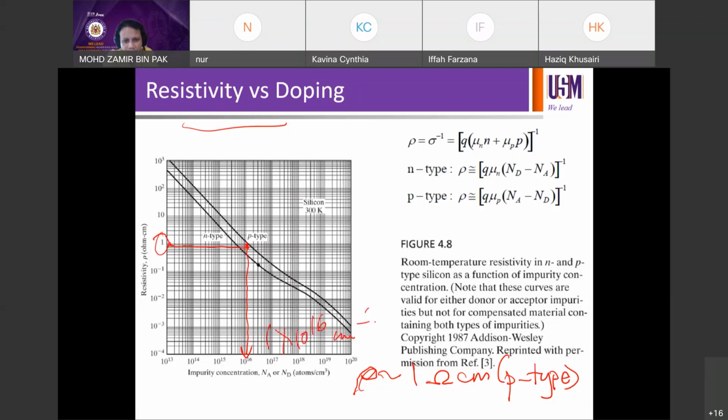Okay. So sometimes when you get a wafer, you don't know the doping level, but another parameter is declared, which is resistivity. But this resistivity corresponds to a specific doping level. So what you have to do is come back to this curve and check. On the other hand, if you're given, say, okay, let's try 10 ohm cm n-type.